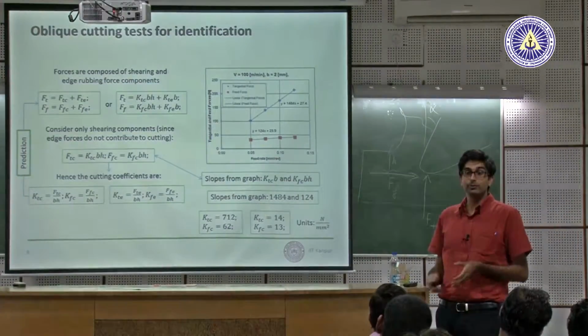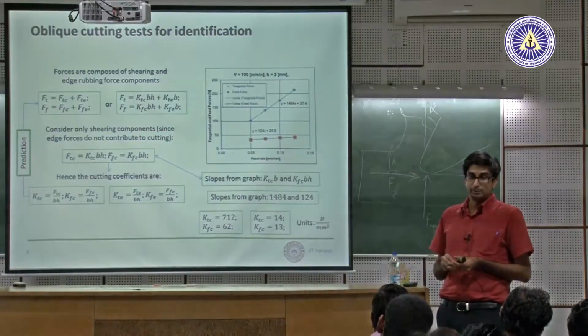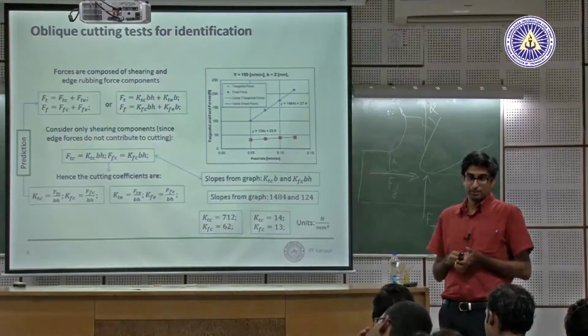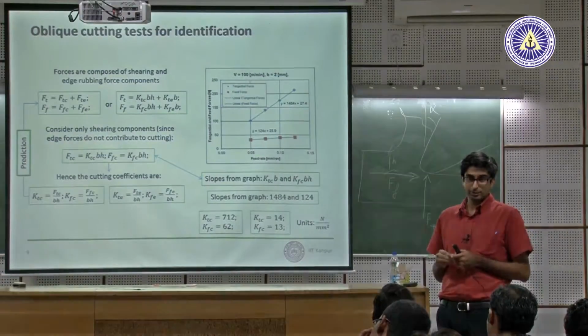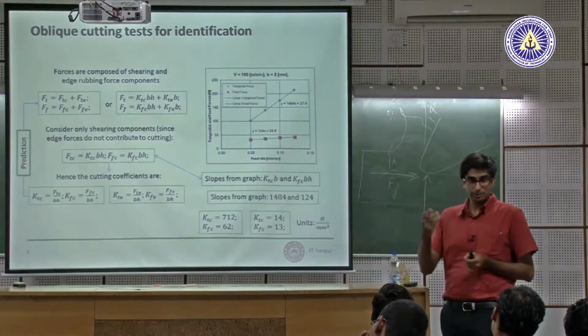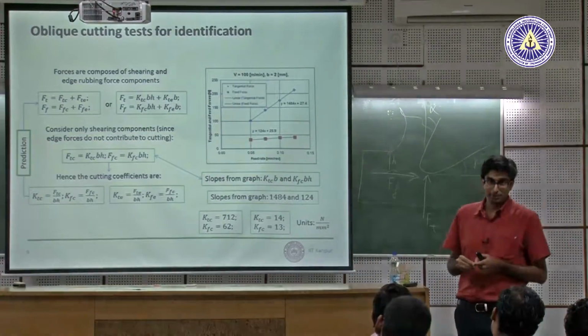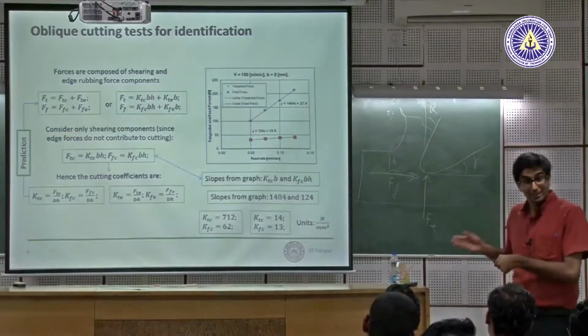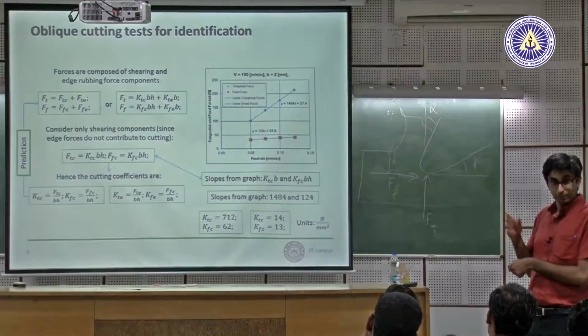Because speed is a function of diameter. We are fixing cutting speed, V equal to pi dn. If you want to keep V fixed, diameter keeps changing, you keep changing speed. And because it's a servo motor, it's very easy to do. So it should also depend on depth of cut. B is the width. So this is turning.